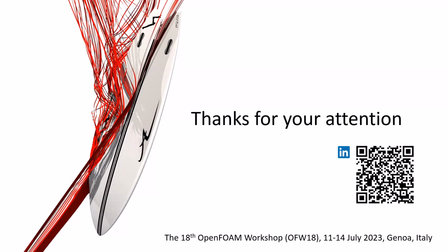So yeah, we tried with CFMesh, but the problem with CFMesh is that it doesn't allow to reach the desired resolution on the wall. Snappy is most suitable from this point of view, and for sure it is not very simple to manage to reach a good quality of the mesh. But just CFMesh, any other code for meshing.